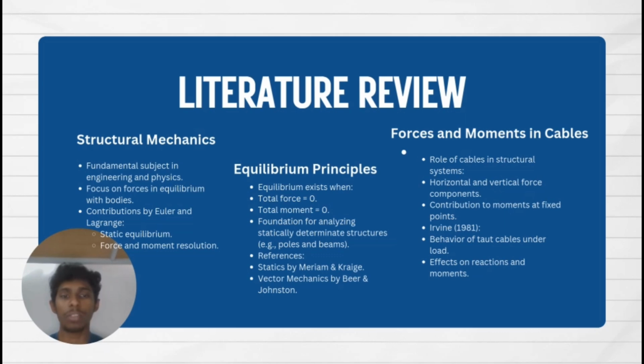Cables usually make up part of structural systems. Cable forces are also discussed with a focus on the differentiation of force into horizontal and vertical components, as well as the moments. Irvine 1981 conducted studies that dealt with the behavior of taut cables under load, their effects on supports, reactions, and the moments. A relevant finding is that cable forces make a large contribution to the moments at fixed points. In this problem, this is evident with the structure and the cable arrangements, which makes it easier to calculate forces and moments because of the symmetry.